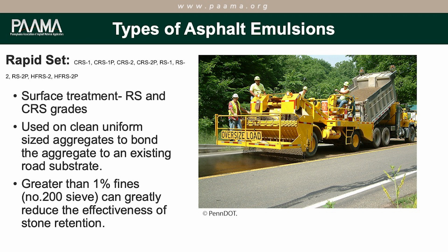So what's going to happen with a rapid set is if you have too much dust on your stone, the oil is going to stick to the dust and not the stone, and obviously that's a problem where we see stone loss.